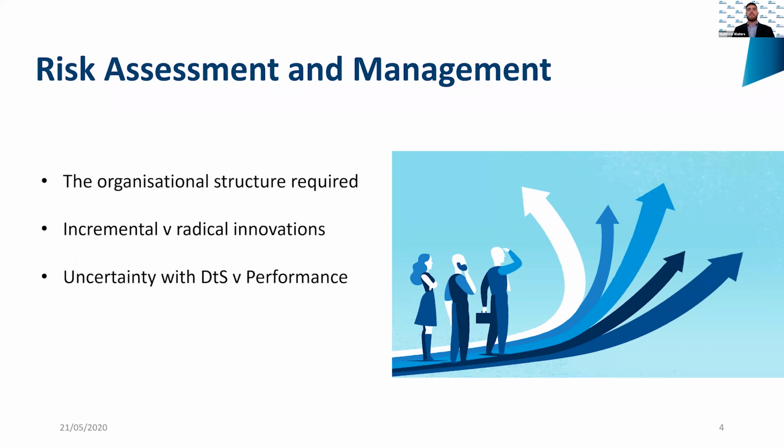Now, if we look at this in contrast to performance solutions, in a performance solution process, it might be the first time that a design, material or form of construction has been trialled. So it's quite different in terms of the risk level. I'm not saying that a performance solution isn't legitimate, it obviously is. It's just that we need to understand how the risk changes and that the process and structure is different to that which we typically need to manage a deemed to satisfy solution.